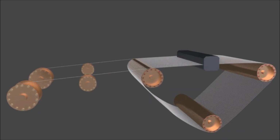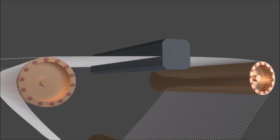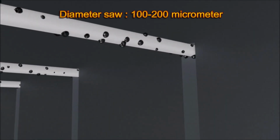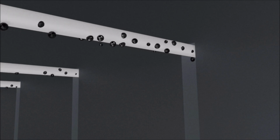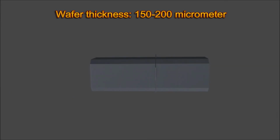The ingot is sliced using a high-precision diamond wire saw. These wires are extremely thin, typically around 100 to 200 micrometers in diameter. The goal is to minimize silicon loss while maintaining extremely precise cuts. The resulting wafers are usually around 150 to 200 micrometers thick. This is actually thinner than a human hair, but despite this fragility, the wafers will become the active semiconductor platform for the solar cell.